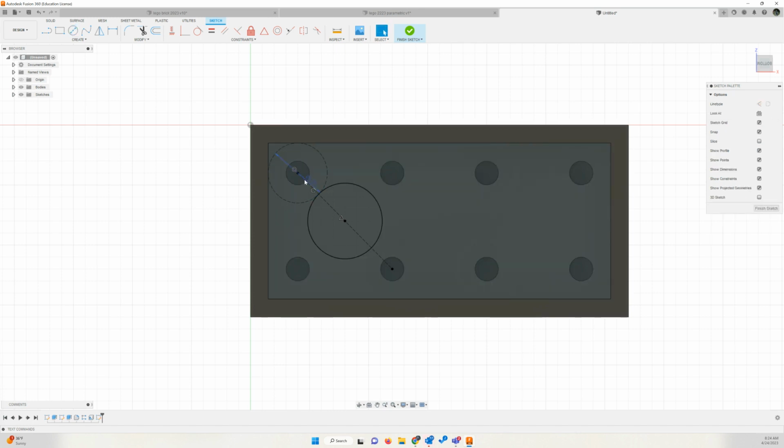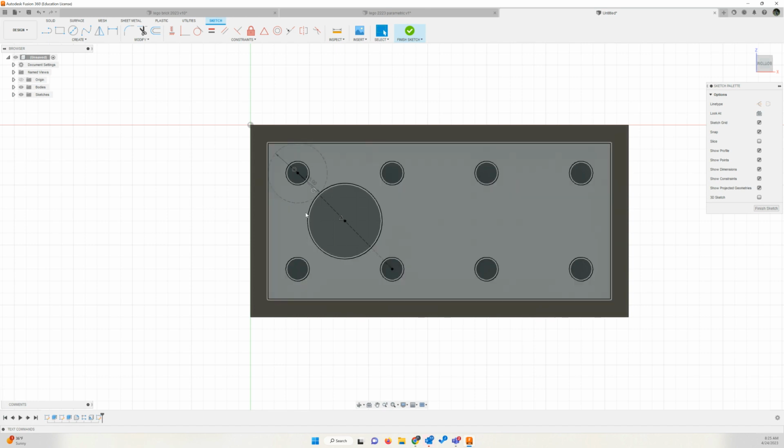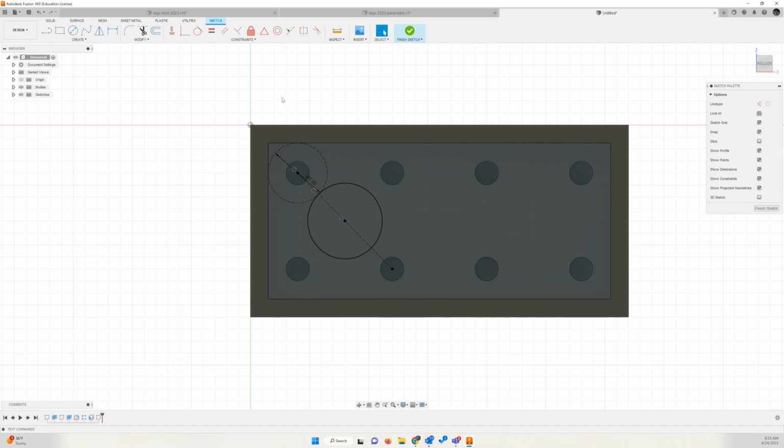If this is a square and this is centered, and it is tangent to this 5 millimeter center diameter circle, it's going to be tangent to the 5 millimeter center diameter circle at these 3 locations. You can draw it and test it, but I guarantee you it's right. Now, the wall thickness, this is not solid, it's hollowed out, and we want it to be 1 millimeter.